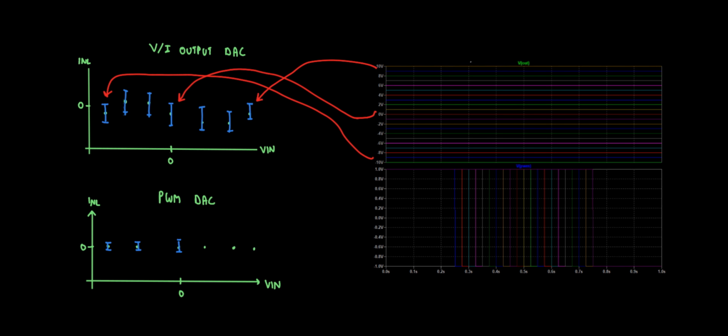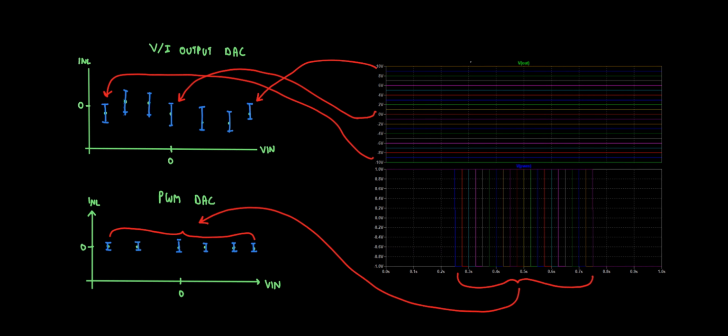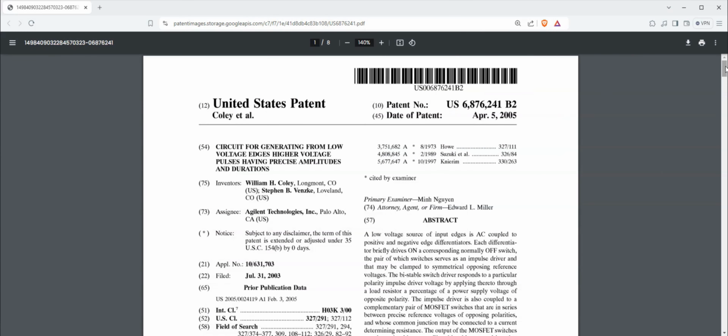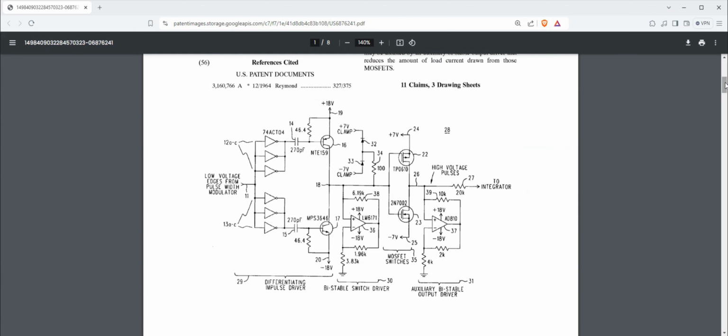Precise timing is much easier to achieve on the part per million or even billion level than similarly precise voltages or currents. The PWM DAC, as implemented in Multislope 4, is described in a separate patent. It consists of a capacitive level shifter driving a complementary pair of MOSFETs which switch the positive and negative references. An additional op-amp unloads the MOSFETs and reduces errors that arise from their on resistance.